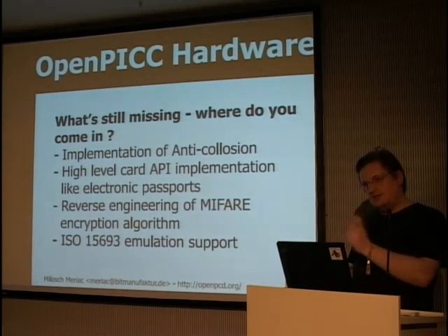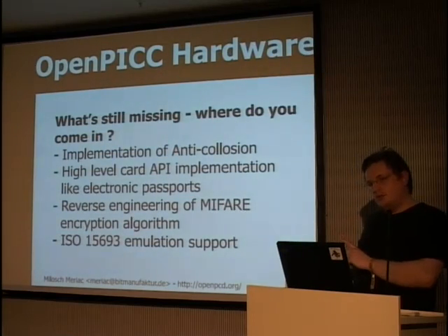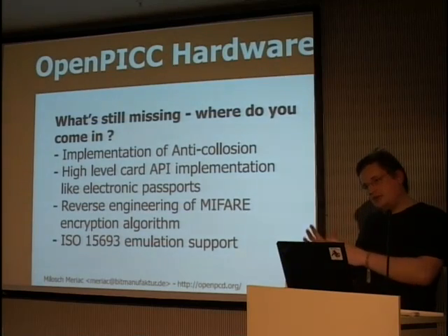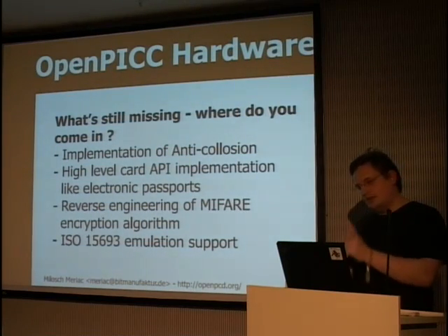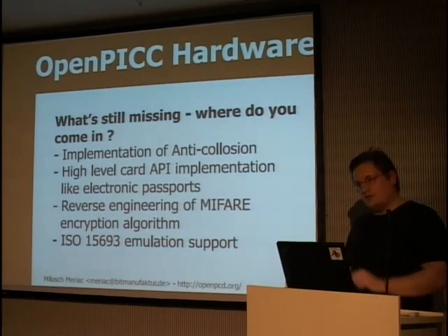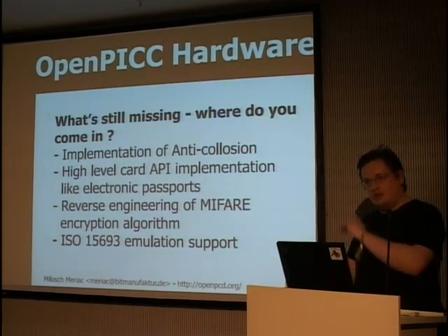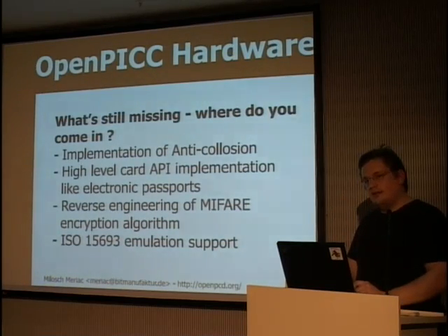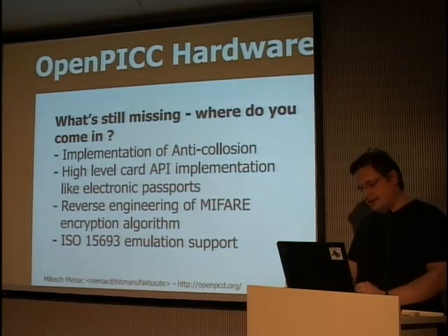So this means that if you have this device, as soon as the anti-collision is over, you are able to take over from the host side. So you can develop a complex application locally on your host PC. You can debug it locally, and it will supply the necessary data over the RF interface and the therefore virtually emulated tag. And because we are in full control, we can behave like 2, 3, or 1,000 devices virtually, because we can basically send collisions easily.